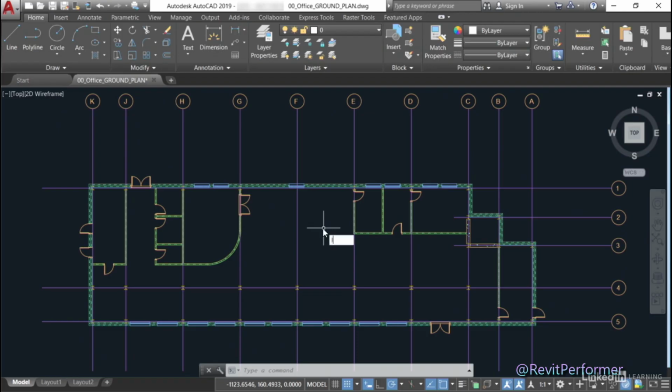So I'm just going to type LT scale, like so. And I'm going to do a global LT scale change. I press enter, and at the moment, the line type scale factor is currently set to 1. You can see that there on the dynamic input on the crosshair there on the screen. I'm going to change that line type scale factor to 50 for everything that is dashed or dotted in this drawing. So I'm going to do 50 and enter.